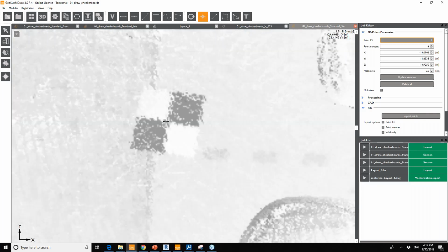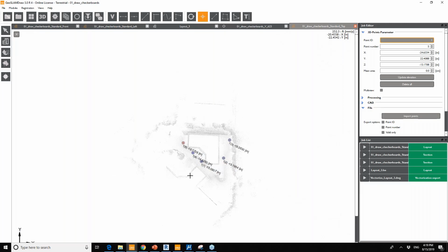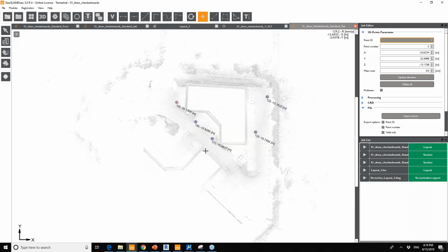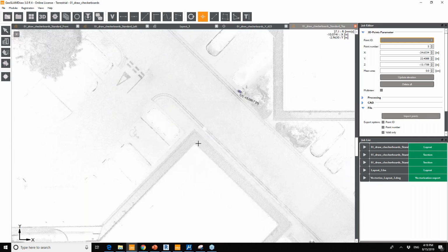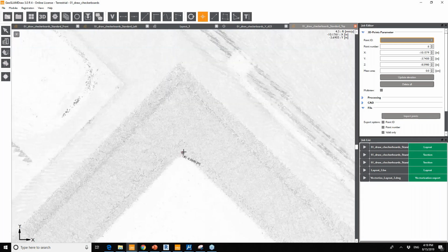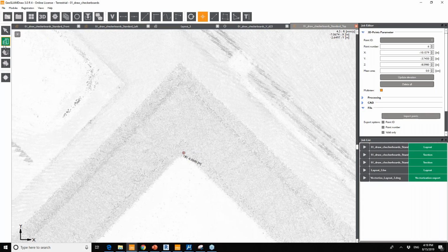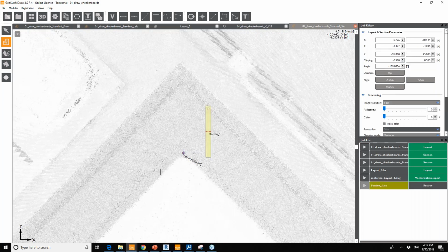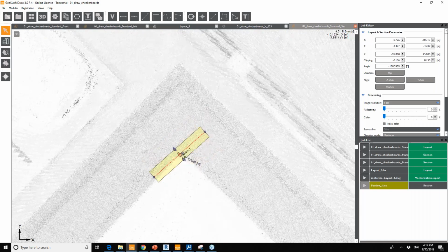If you, for instance, measured a corner of the building and you want to place the point there, and it might not be quite visible, you're not sure if you place the point on the top of the corner of the building or right below it, there is this multi-view function which can be handy to double check the point from the side view. So I ticked multi-view, and I'm going to create a quick section through the roof of the building with a point right in the middle.